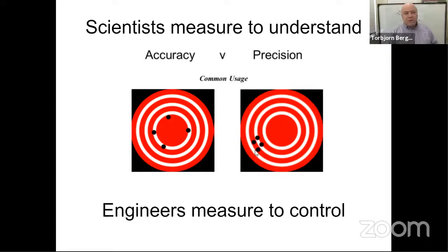With this, we don't have random errors, we have specific errors, and we have to actually physically fix those in the system in order to get it to be accurate. So the ISO standard defines accuracy as closeness to the true value and precision as closeness to the other measured values.